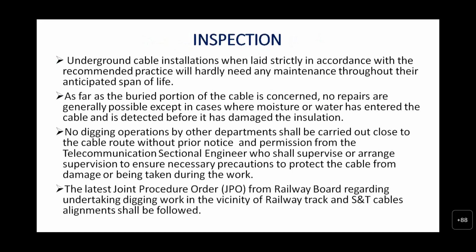During the inspections, underground cable installations, when laid strictly in accordance with the recommended practice, will hardly need any maintenance throughout their anticipated span of life of 20 to 25 years. As far as the buried portion of the cable is concerned, no repairs are generally possible except in cases where moisture or water has entered the cable and it is detected before it has damaged the insulation.